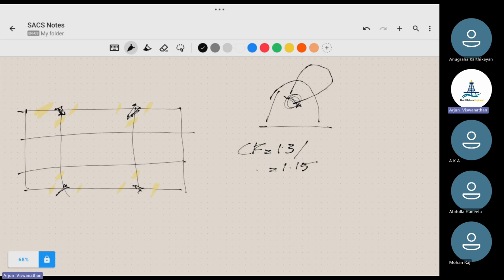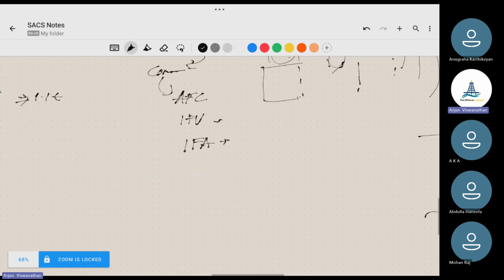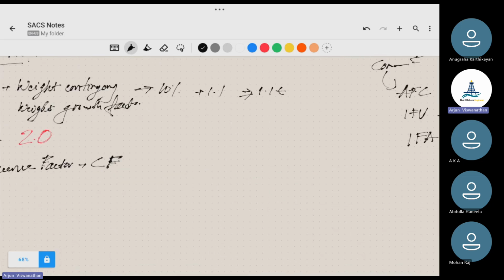So what we usually do is, because splitting the factors here differently is a very tiring process, and in subsea we don't care much about the extra weight on the member unless it fails, we will directly go for 1.3 in that case. So I will come over here and I will select 1.3. So, consequence factor clear?